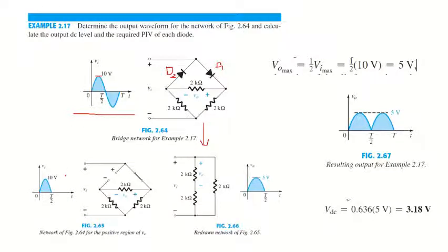So coming here, for the positive lobe and having the maximum voltage of 10 volt, we are using the ideal diode. So 0 to T by 2 is the time period. For the positive half cycle, this will be on and this will be in the off state. So the direction will be like this and this. So the current will flow and this will be off. So the current will flow in this direction.